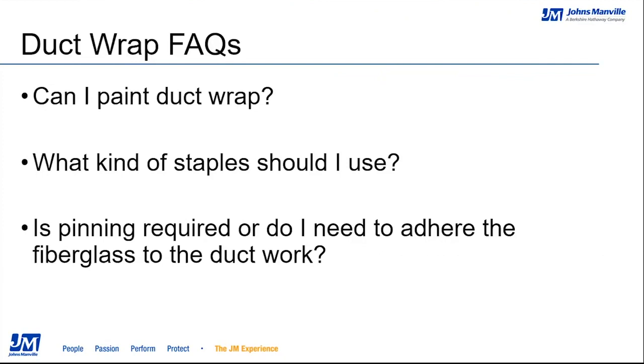As far as using adhesive to adhere fiberglass to ductwork, we've gotten this question a lot recently as well. We do not recommend using adhesive to attach your fiberglass to the ductwork with any sort of adhesive coverage. Again, it ties back to the flame and smoke spread index, the 25/50 rating that we get on our products. When you start adding in a glue, we don't know if that glue is flammable or not, so it can basically ruin the product warranty and the UL rating if you start using adhesive in that application. The other thing that could impact it when you're using adhesive is, I talked earlier about having less than 25% compression to reach your installed R values.